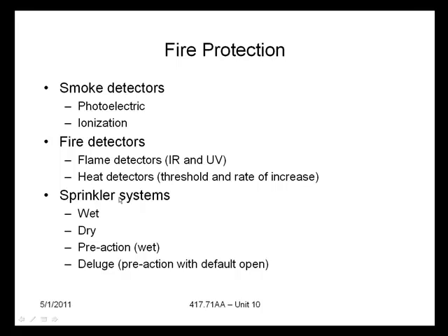Now, fire prevention includes a certain number of devices here. You've got smoke detectors, photoelectric devices. It's a beam of light where the light is interrupted based on the obscuring nature of smoke. You've also got ionization detectors that rely on radioactive energy to detect smoke as well.